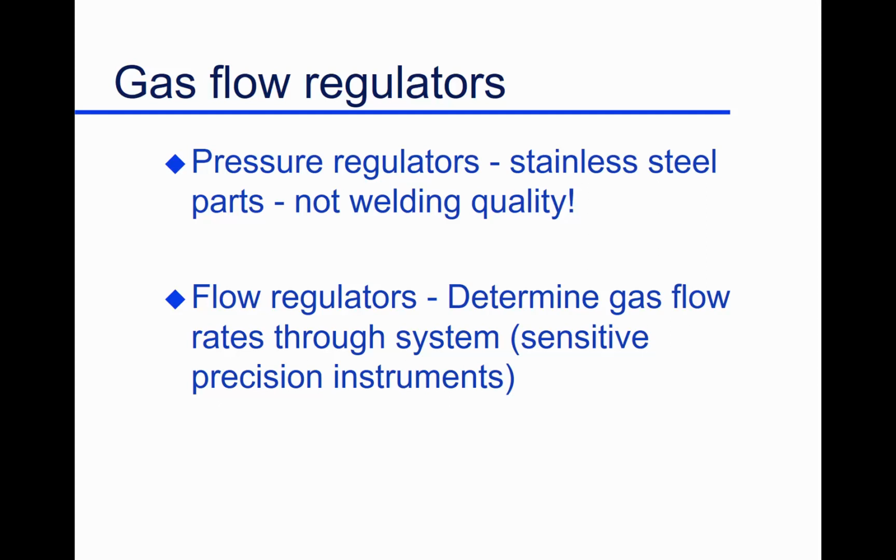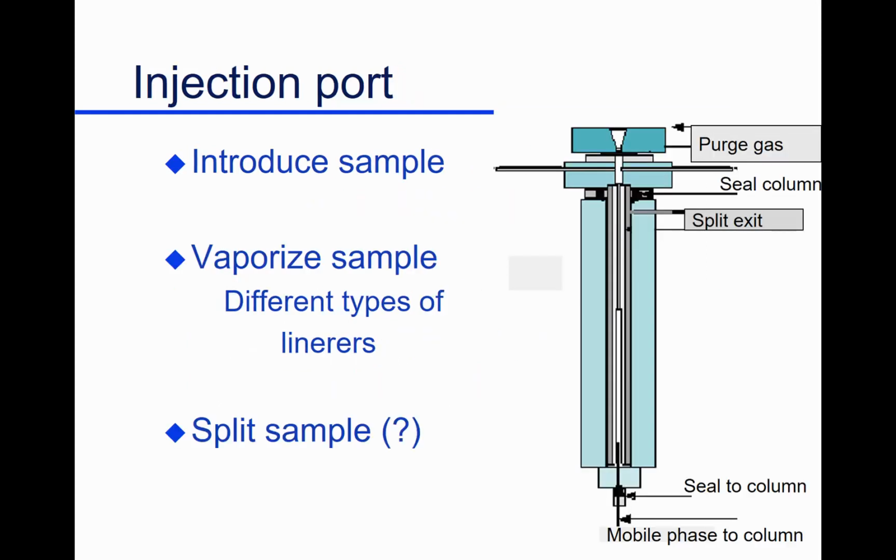And when you run this type of equipment, you will actually control it either by the computer or you'll do it manually. If you do it manually, we always tell people, don't keep on turning until it stops. Your gas is going to stop before that. If you turn it until it stops, you're going to crunch my regulator. They're very delicate instruments. So now here's where we put our sample into the system.